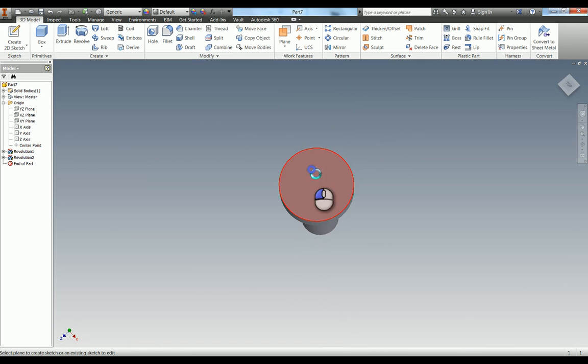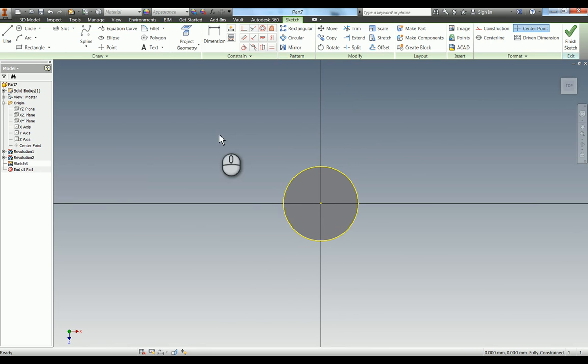onto the top profile. I have this tool here which I haven't used yet, which is the polygon tool. So it works very similar to the circle. It's a centre point start, and then you click to the outside. And I'm going to change it. Well, it defaults to 6, and we're trying to draw a hexagon, so that's absolutely fine. And I'm going to draw it in line here, so just to match the drawings.